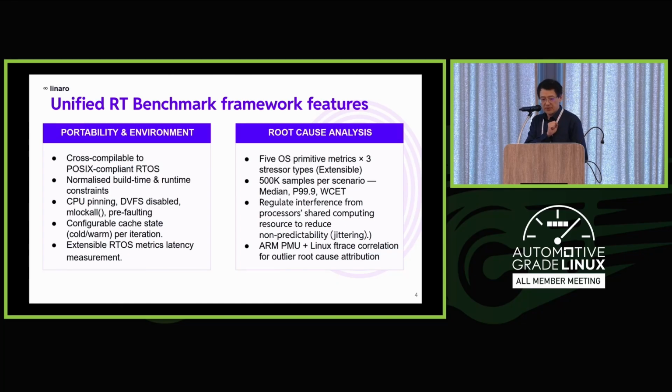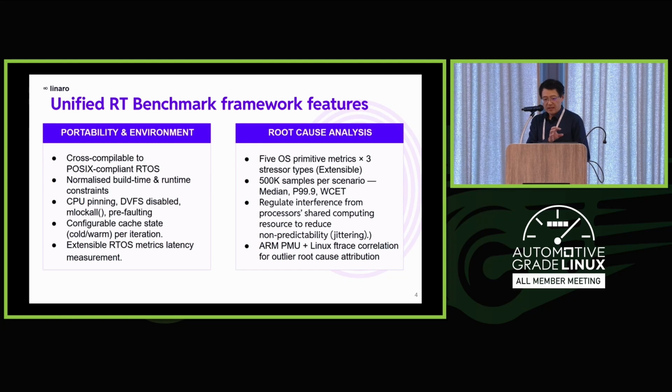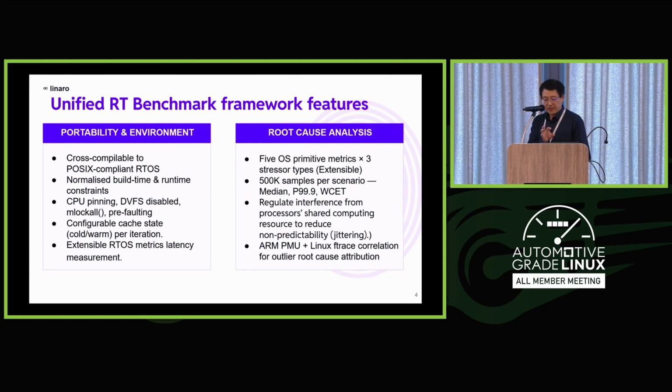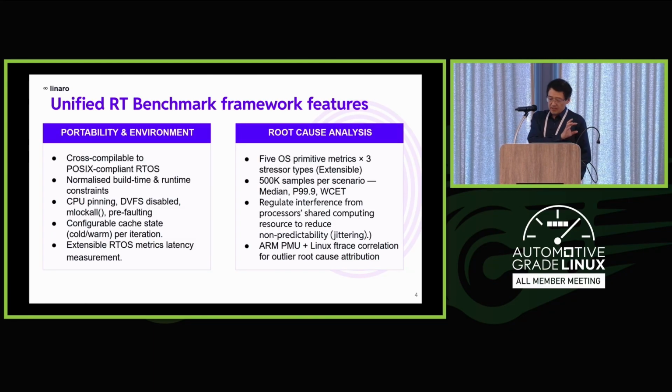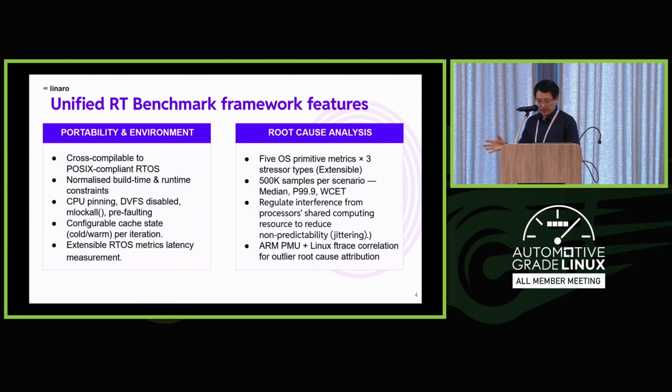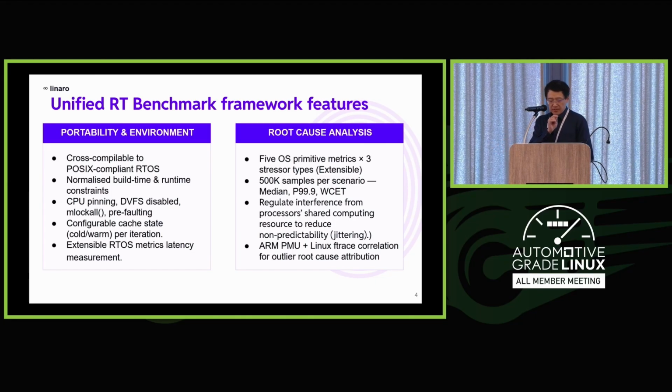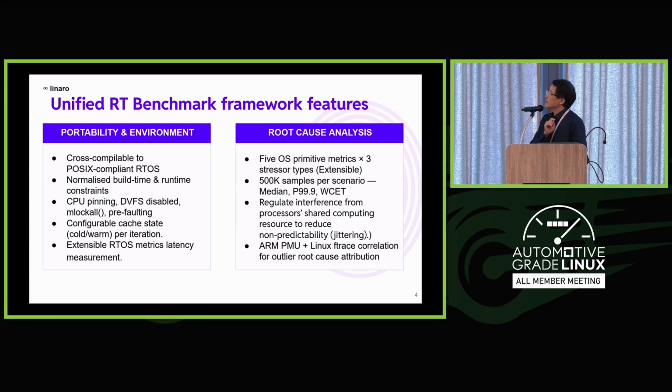The second design goal is that we also want to go beyond getting the results and identifying the worst-case execution time. We also need to understand the root cause. Essentially, we're leveraging the ARM performance counters to pinpoint whether an outlier latency is contributed by hardware event noise. That is one technique we're using.